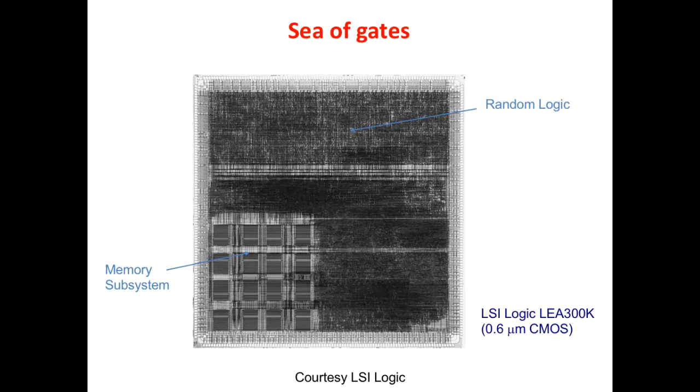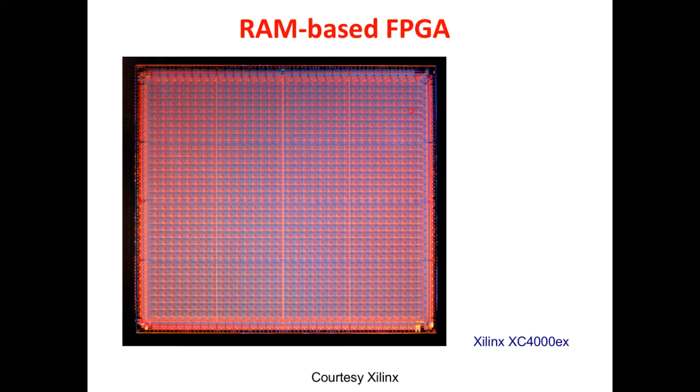On the other hand, if you look at an FPGA, it is extremely modular. You see, every small block consists of some logic and an SRAM on which the different lookup tables are written. These blocks are all connected by some lines that bring the power supply, the ground, the clock, and so on.